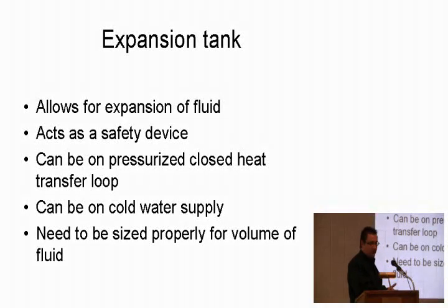It's, let's say, 2:30, 3 o'clock in the afternoon. Your collectors are still sitting out there in the sun baking away, and all that fluid in there is getting hotter and hotter. So it starts to boil out of your collectors, and it needs somewhere to go. And you don't really want it blowing off your relief valve. So an expansion tank is put in the system as a safety device to absorb that fluid.